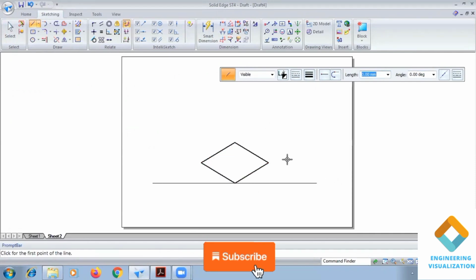Now vertical height we need to give the height of 50 mm. One line I will draw, length of 50 mm. Then go to move command, create a copy of it, or either you can directly do it like this. Length 50 mm directly we can do. Angle is 90 degree. Okay, now construct the top face. So here the cube construction is done, guys. The cube we have constructed.